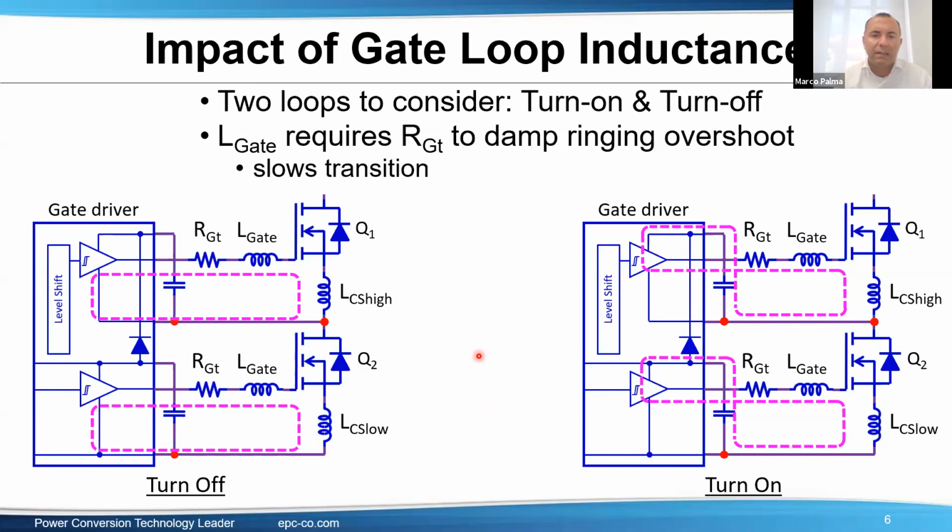But the best performance I've seen so far is with optical probes, which are able to measure the VGS of the high side while it's switching and floating up and down in a converter. But it's not really easy.